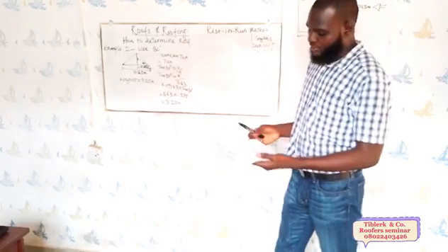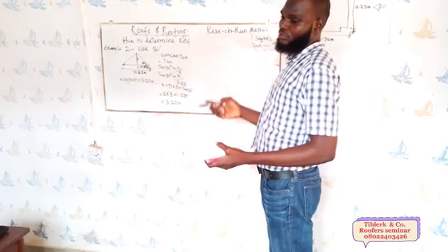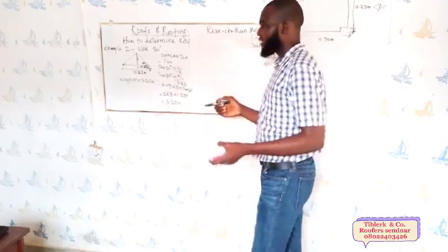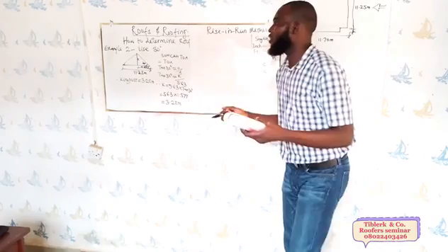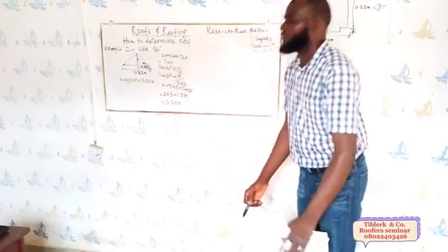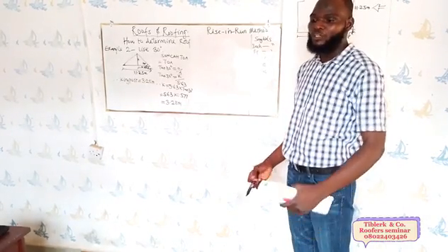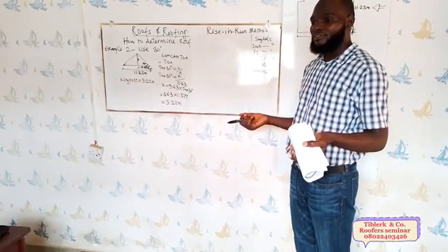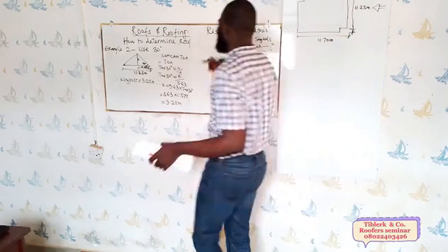The percentage is easier when the roof pitch is specified in percentage. We have to use 50% of the run. The rise should be 50% of the run. It's easy. It is just the run times that. Okay, let's do that.